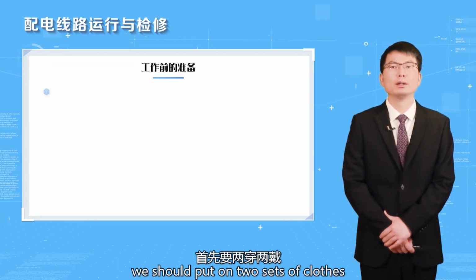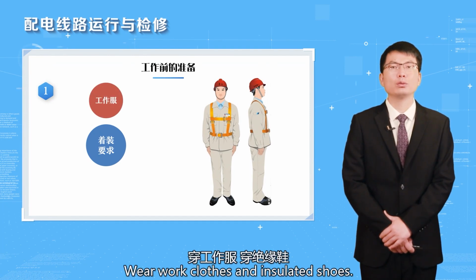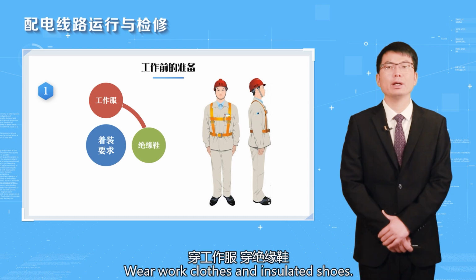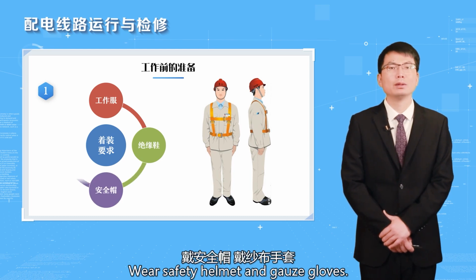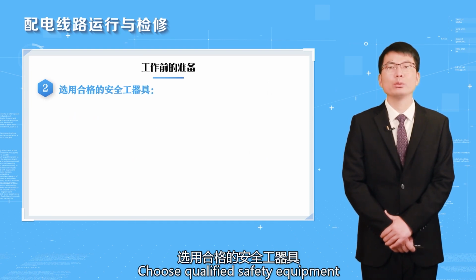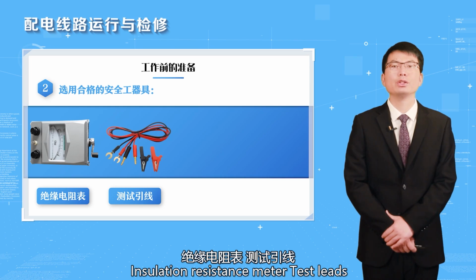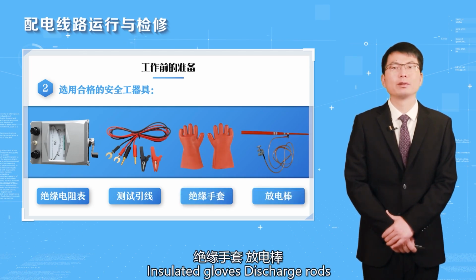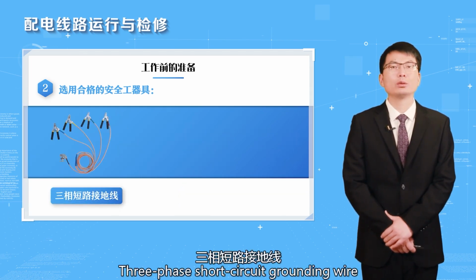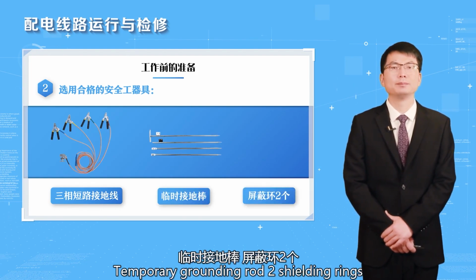First of all, we should put on 2 sets of clothes and 2 sets of shoes. Wear work clothes and insulated shoes. Wear safety helmet and gauze gloves. Choose qualified safety equipment. Safety equipment includes insulation resistance meter, test leads, insulated gloves, discharge rods, 3-phase short-circuit grounding wire, temporary grounding rod, and shielding rings.